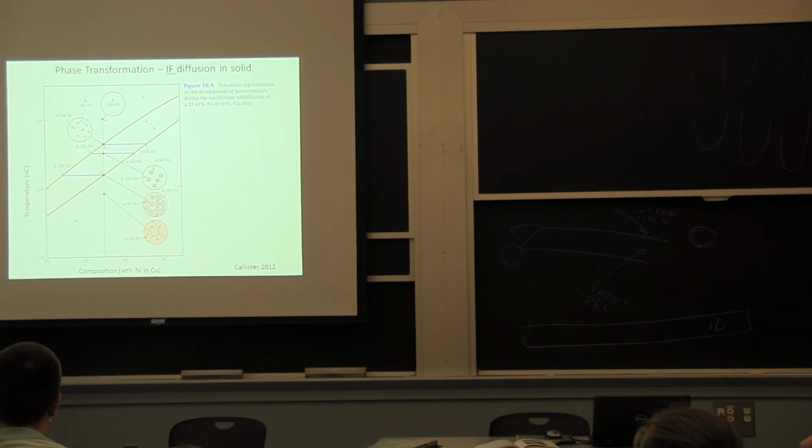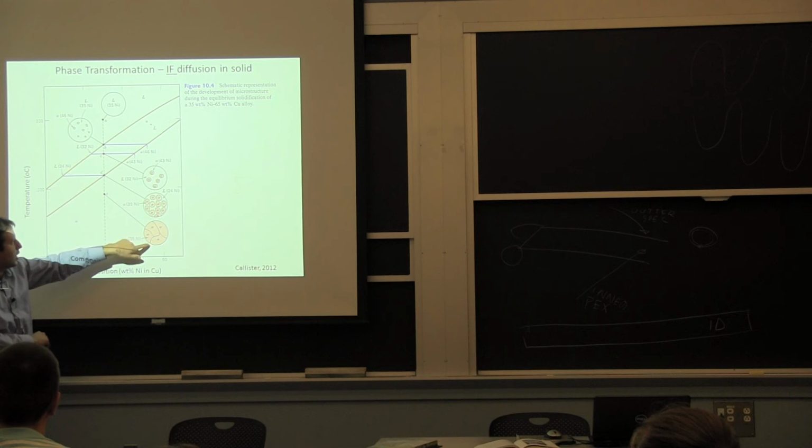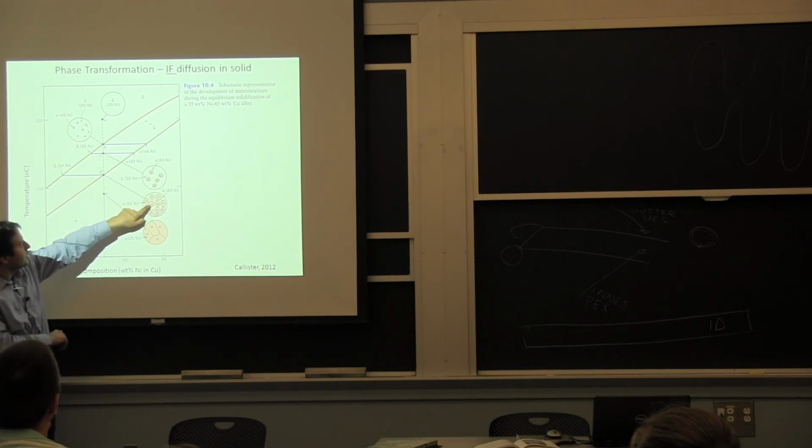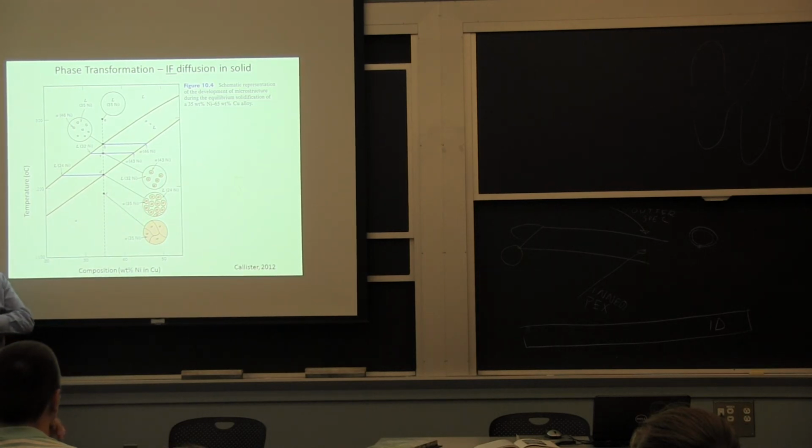So from 46 to 24, there's one part that, in the interest of providing an overview, I didn't mention. The reason I'm going back to it is the phase diagram can't always be right. It's just a question of whether you really have the conditions for that to happen. If you want to end up at E with the same composition, 35% nickel everywhere, you need the higher concentration of nickel to diffuse back into the new solids that are being formed. And that's the part that's fairly unrealistic.